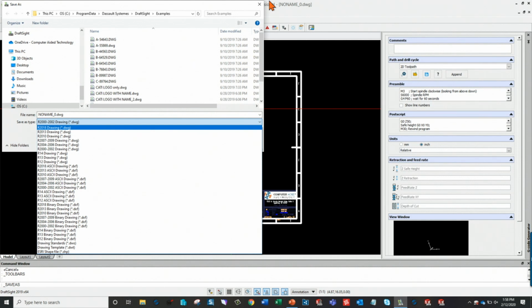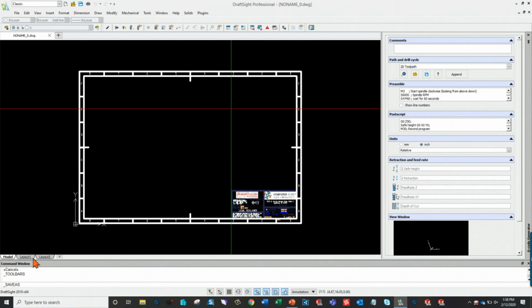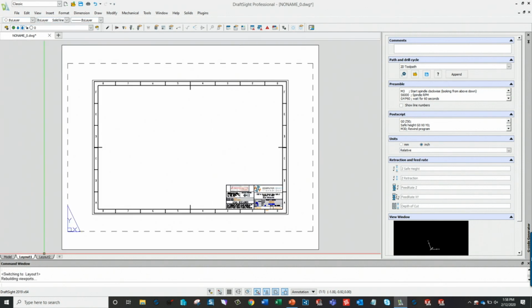Just complementing a little more of that, those frames, we actually use on the layout. So on the model, we just flatten. If you want to do paper space, yeah, you could do that. Okay, and then can we add viewports like in AutoCAD? Yes, you can. Right now I'm on model here, but if I go, let me close this right here. Here's where you can go to layout and stuff for paper space.